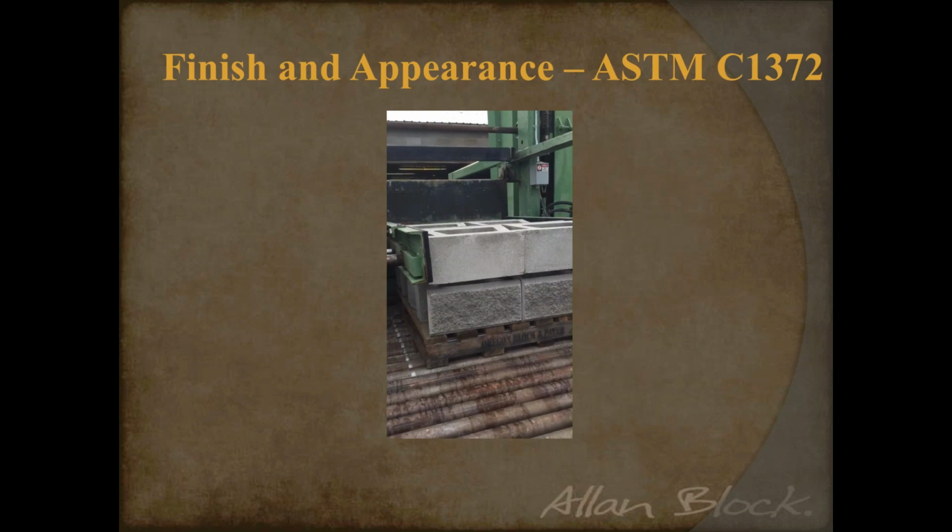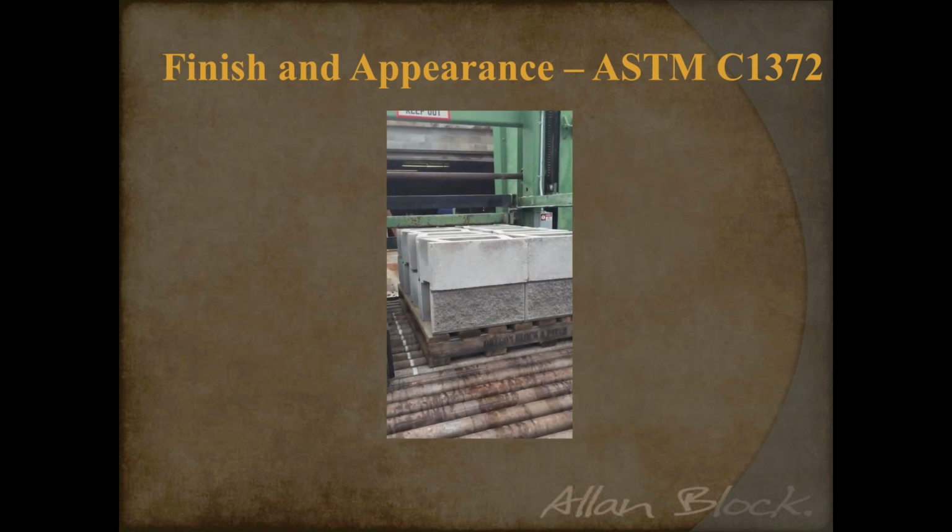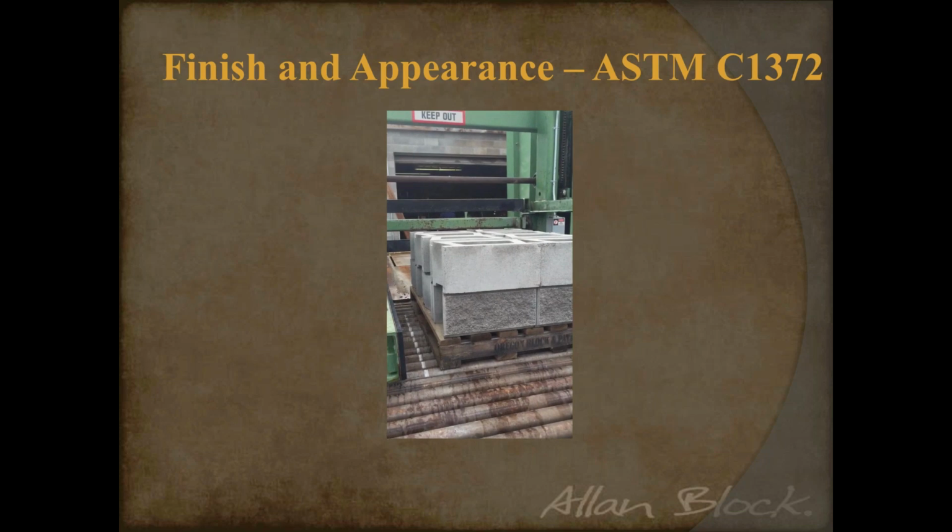When it comes down to rest, it's going to very gently rest so that the lip is down, and again it sets now relatively level at the top of the second course. So the third course will be right side up again, and then the fourth course will be upside down. So very careful to use the machines, and produces a really, really nice block without chipping.